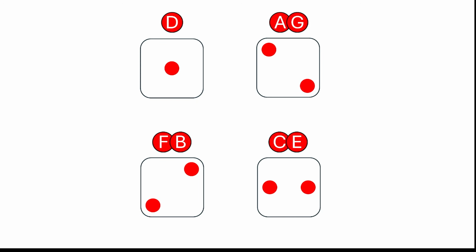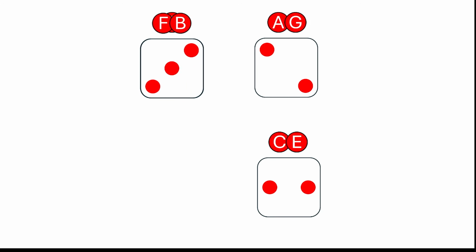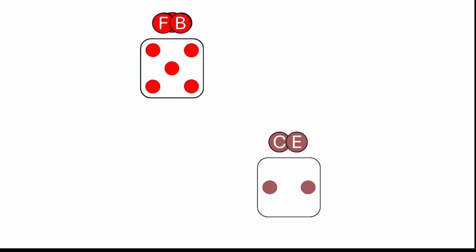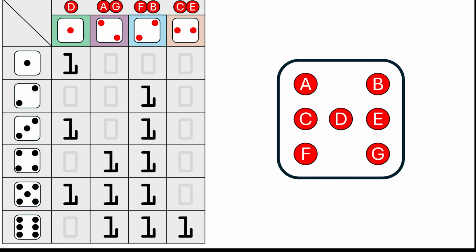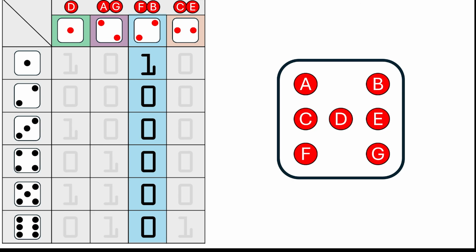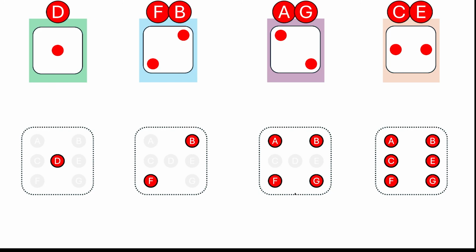For example, if I want a 5, I would turn on D, F, B, and AG and then disable the CE. We can draw out a binary truth table for this to get a better look. Here, the pattern for 2 is highlighted, and it appears always except for 1. We can overlook and invert this logic using a PNP transistor to simply keep it always on except for the dice face 1. Let's turn this into a circuit now.